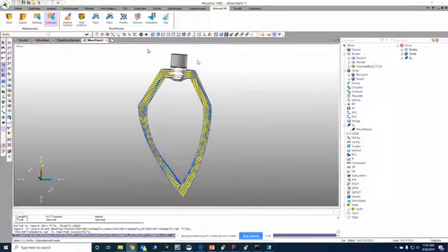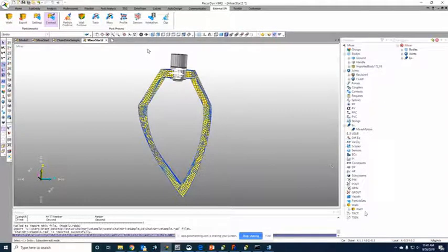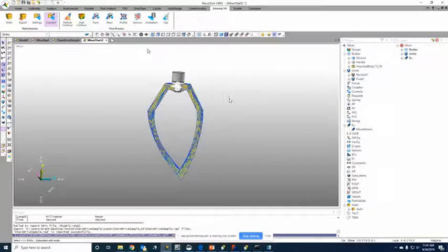So we had just created a wall in RecurDyn, and so if you still need to do that, Mark, just press the wall, and then click on the patch that was just created, and it creates this wall here. And so this wall can be renamed if you want. I'm just going to leave it as wall 1, so that defines that interface between RecurDyn and Particleworks.